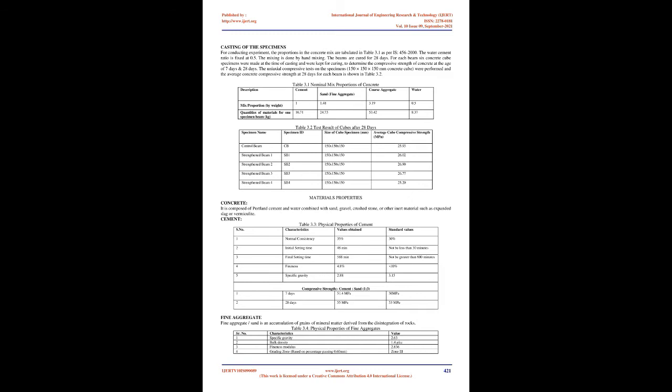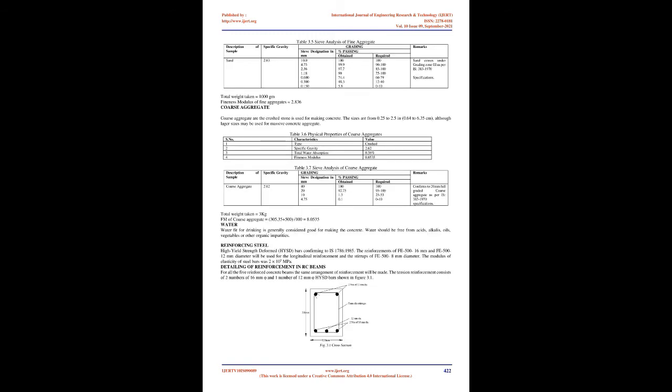The carbon atoms are bonded together in microscopic crystals that are more or less aligned parallel to the long axis of the fiber. The crystal alignment makes the fiber very strong for its size. Several thousand carbon fibers are twisted together to form a yarn, which may be used by itself or woven into a fabric, Fig. 1.2. Glass fiber reinforced polymer, GFRP.